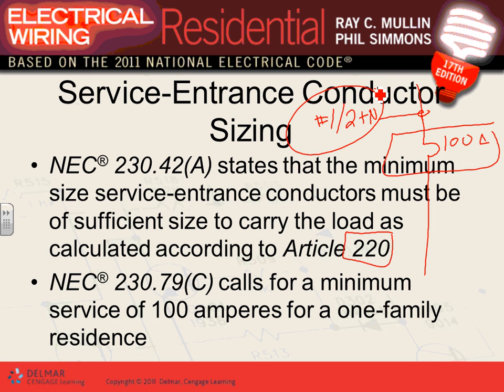Is it number 1, the size for 100 amp? Yeah. Cover, all cover. Number 4? Okay, there you go. There's mistake number 1. Number 4. So that's how you size it. And you size it based on the overcurrent protection device, and the overcurrent protection device is sized based on the load.